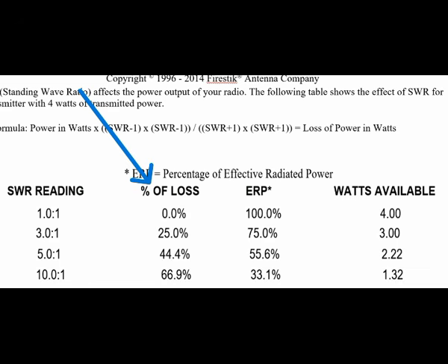Most of this loss that people focus on and claim is in the coax, or power bouncing back from the antenna and going back to the source, most of that power is actually just setting up a standing wave on the transmission line, and power isn't going both directions at the same time. It's only going out, and this mismatch only causes a variation in impedance along the transmission line, and we can prove that that variation in impedance does not represent a certain percentage of power loss.